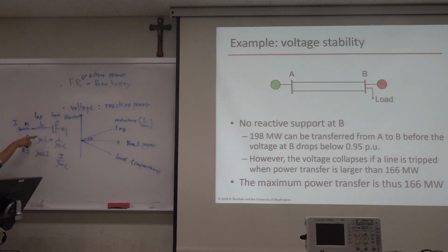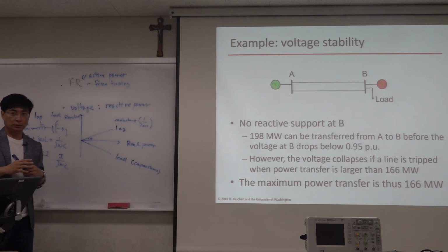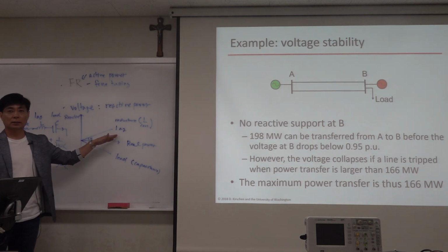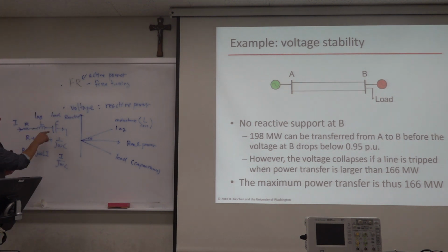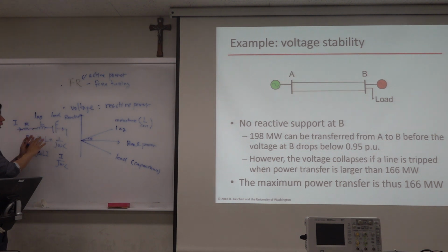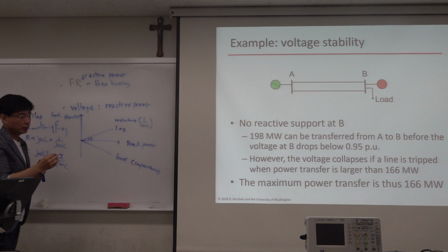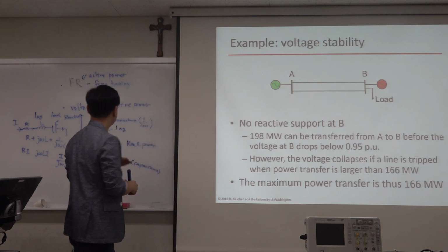It's because when you look at this, coil impedes current flows. Right? So when a voltage is applied here, this coil component impedes the current. So the phase of current is behind the voltage. Do you see what I'm saying? So that's why this is called lag. The opposite of lag is lead. And the reason why this capacitance is called leading is because this capacitance has some energy already stored in it. So even if the voltage is applied here, it can immediately supply some current from the stored energy. Okay? So the phase of current can lead the voltage, intuitively speaking. So that's the meaning of lagging and leading.